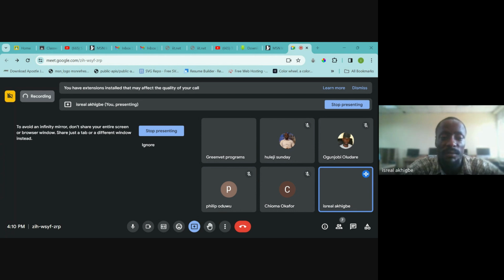Now, in belt drive power transmission, transmission occurs through friction. I want you to understand that belt drives actually work in pair with pulleys. So after this session on belt drive, we're going to be talking about pulleys. When you see a belt drive, it is to be used with a pulley or pulleys. We have different types of belt drive. The most common you will find is the V belt. The V belt sits in a V groove pulley. In the resource I've dropped on the Google Classroom, you see some videos to show you practical applications, but we'll still have our own discussion here.